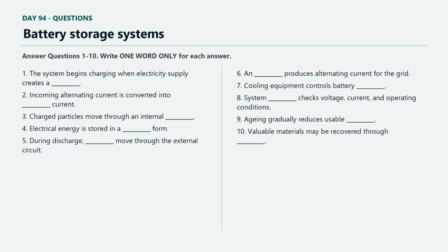A control center can instruct the storage plant to absorb part of the excess rather than reduce generation or overload the network. The instruction considers market prices, network limits, expected demand, and the battery's present condition. Charging is not automatically useful whenever supply is high. The plant must retain enough space and remain within safe limits.